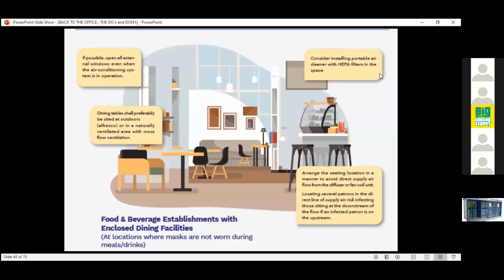I think there are many of them in the industry and in the market now. But be careful, as I mentioned, each air purifier has a specification called CADR. The CADR tells you, for a certain air purifier, the capacity of the area it can supply. So you have to look at how big your space is and how many air purifiers you require.